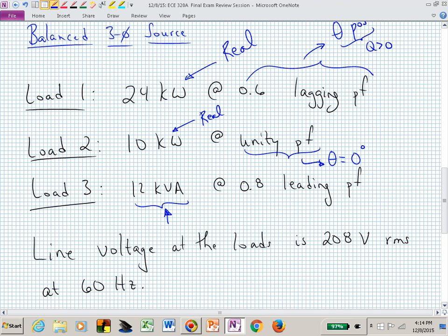All of our powers are volt amperes, but we use units of volt amperes specifically for what power? The magnitude of the complex power, or that's the length of our hypotenuse, isn't it? So this is the magnitude of S, and that's what we're calling the apparent power.